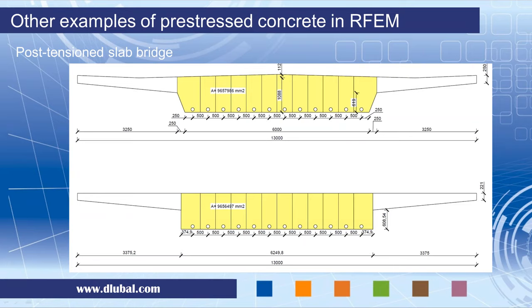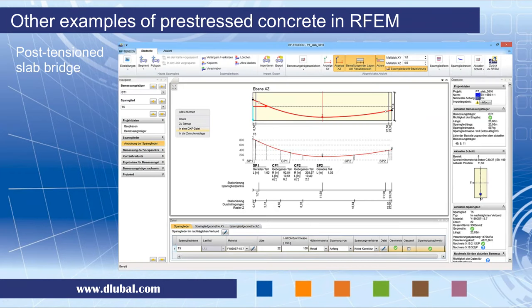You see here the exact shape of the cross-section, and if we simplify it, then we define these result beams. Each result beam would contain one tendon, and then we can use RFEM to calculate the real 3D distribution of stresses caused by the moving loads. Via these result beams we can design each strip of the slab separately.